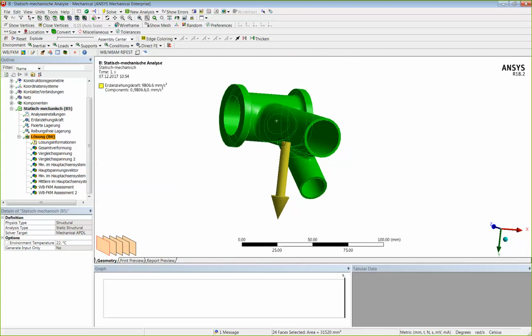The question was also, is there one ACT for shells and for solids? Yes. The structural stress concept is to be expected with solids in the moment and only with solids. And the nominal stress approach for welds is expected to be with shells. And the unwelded is to be expected with solids.